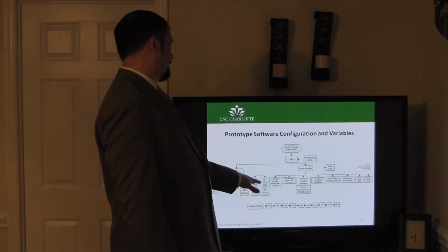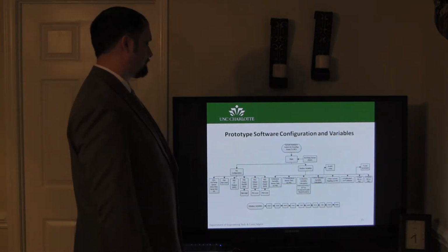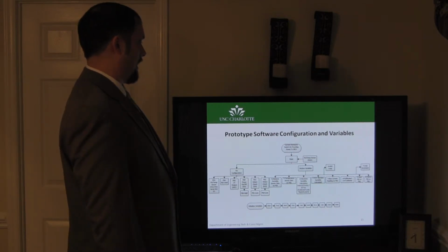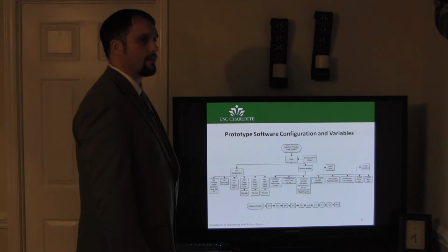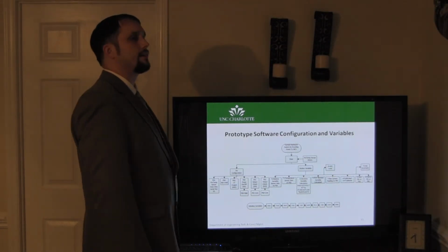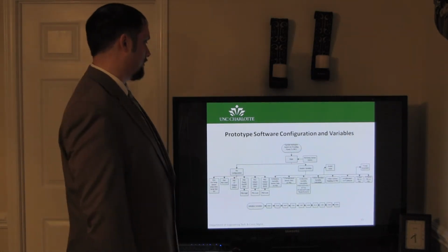And then we have 3 pins that are configured for digital outputs, and those are to drive the Darlington pair ICs. And then we have an additional pin that's used to power on and off the micro through a transistor.